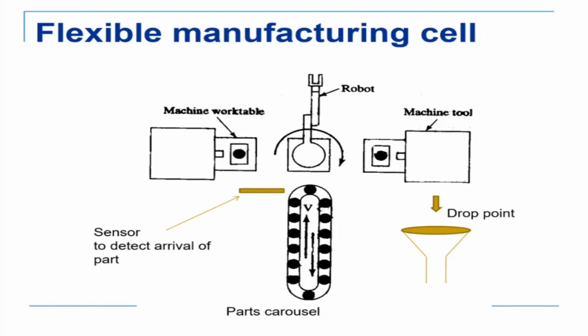So everything has to be optimized, and this actually shows the difficulty in robot programming: the robot program has to be optimal, and after it is optimal in terms of time, it has to ensure safety, and it has to guarantee that with all the errors that are there in terms of resolution, accuracy, repeatability, there is going to be no damage anywhere. And that is something which is very expensive for application of robots.